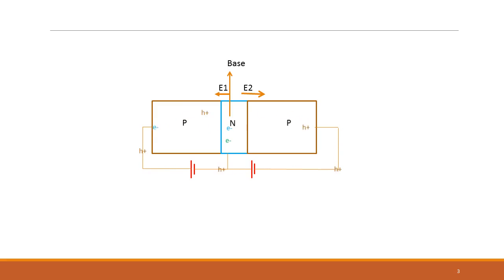Okay. This material on which the two junctions are formed is called the base. This is the base material on which you form the junctions. This p-type is emitting the holes. Okay, you saw that, right? This is emitting the holes, and they then diffuse here. This injects the hole or emits the hole, and it's called the emitter.